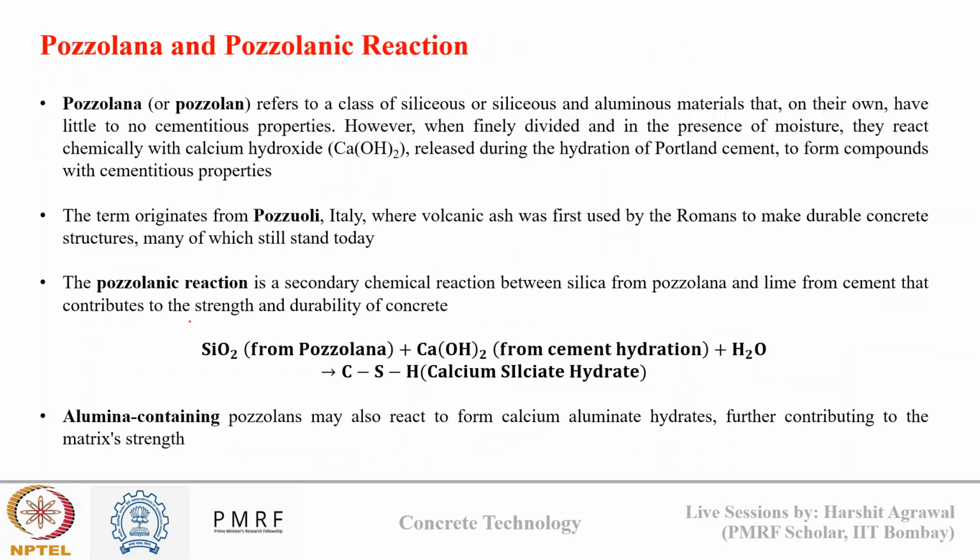Now comes the important part. Why are these produced SCMs reactive in nature? The SCMs that we have produced are also known as pozzolans, pozzolana or pozzolan, and they all have an amorphous nature that was imparted to them during the rapid cooling or grinding process. That's why they have the ability to replace a certain portion of OPC, through what is known as the pozzolanic reaction.